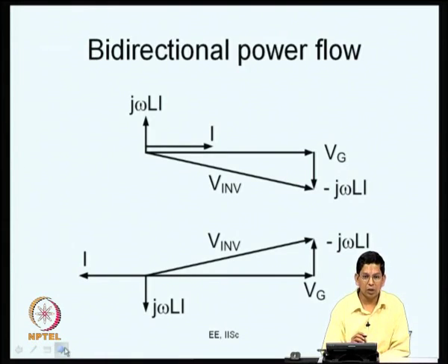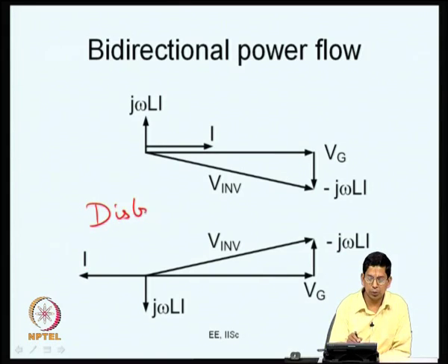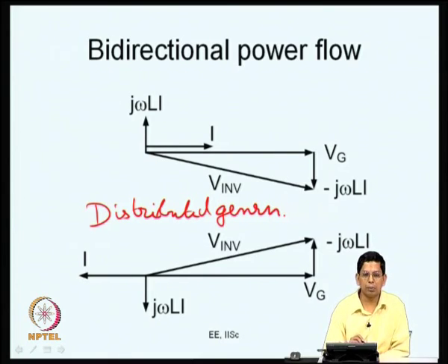So, you can draw current at unity power factor, and you can also draw near sinusoidal currents. If you want the power to flow in the opposite direction, it is possible now. This is what you do in distributed generation. Let us say power is available from a photovoltaic cell or so, you want to pump that power into the mains. This is something that you do typically.